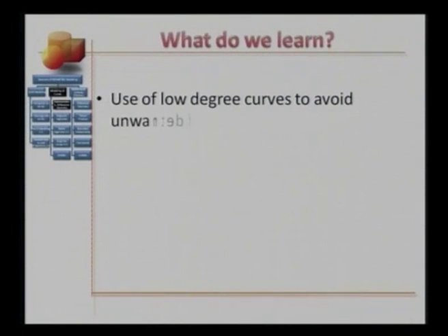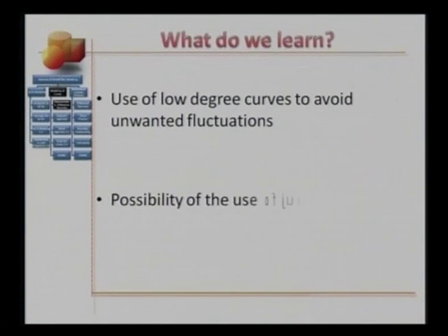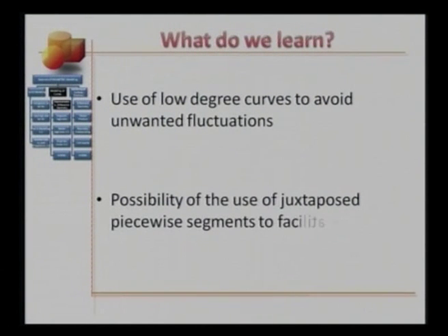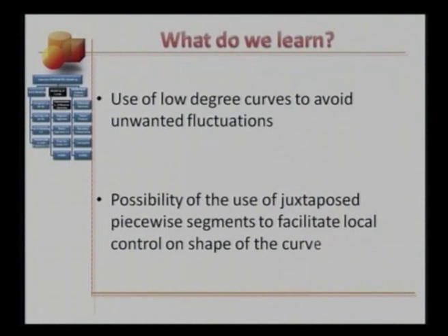What do we learn? Use of low degree curves to avoid unwanted fluctuations, and there is a possibility of the use of juxtaposed piecewise segments to facilitate local shape control of the curves.